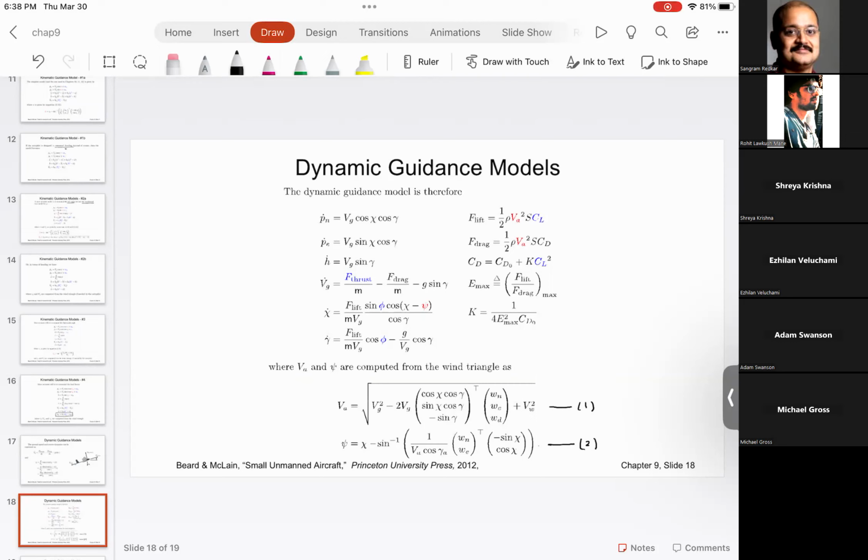But right now, what I want you to understand is these are the equations, and these equations are shown in continuous domain. But what we do is we actually use the discrete or digital versions of these equations and program those on the autopilot, and then use that autopilot to control the control surfaces, as we integrate or execute these differential equations step by step in a discrete form.